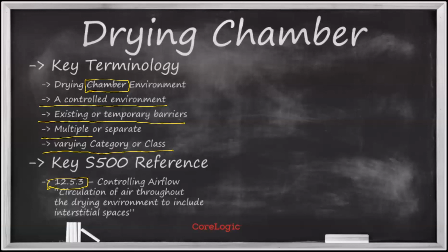These are all interstitial spaces and cavities and voids where, if there is a wet surface present, air needs to circulate into and out of those spaces. In my drying chamber, my drying environment, that air movement becomes that communication, that transportation, that blender that ensures all of that moisture travels out of those spaces into the mechanical systems I'm using for humidity control or ventilation. And that air is subsequently replaced by air that is going to promote the drying process, right? We really have to think almost like we've got X-ray vision when we look at how we establish these environments and establish control over these environments.